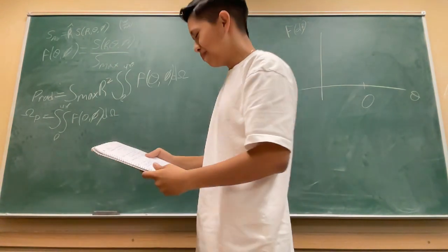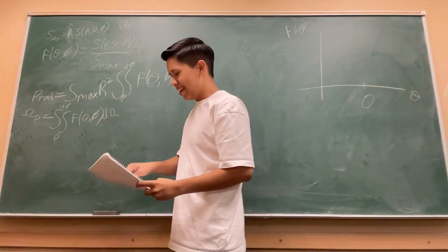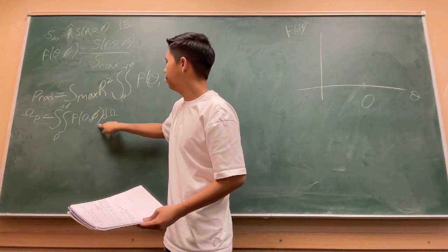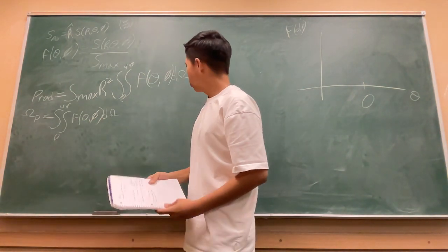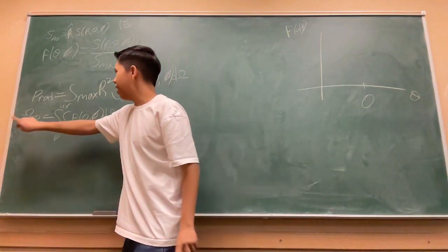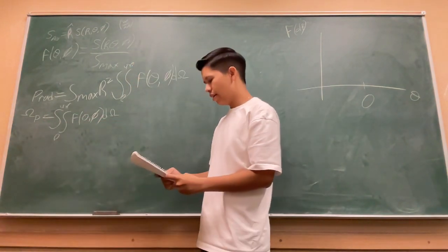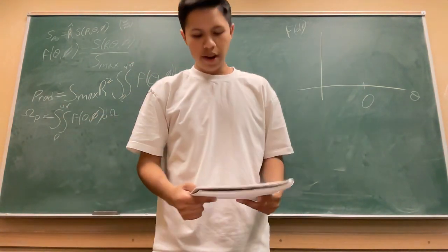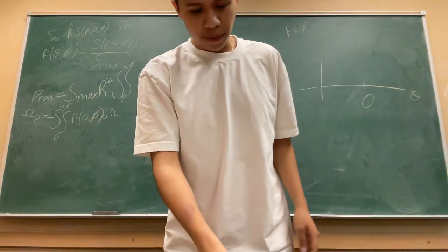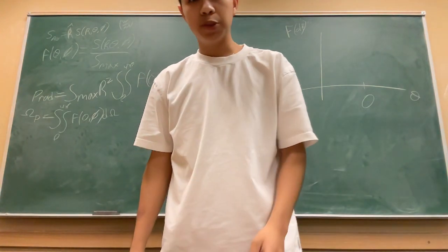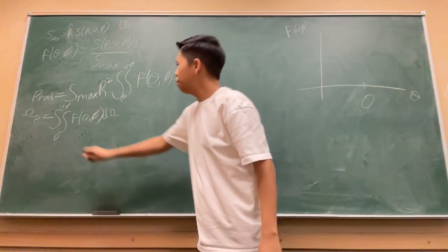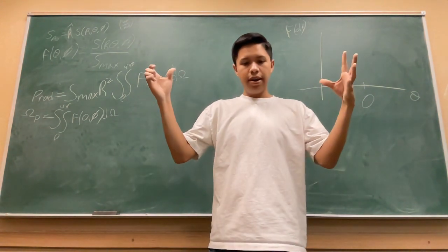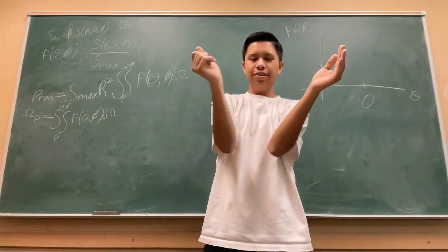So before we do that, this normalized radiation intensity for an isotropic antenna will be 1. So for an isotropic antenna, we're going to have a pattern solid angle of 4 pi, because we have 1 inside and then we integrate that from 0 to 4 pi, we're left with 4 pi. Okay, for anything else, we're going to have a pattern solid angle smaller than 4 pi. And a pattern solid angle is a solid angle. 4 pi, that's a sphere. So anything smaller than that, we're going to get a cone.